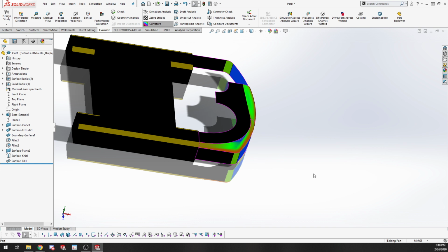Even though this is flat and this is curved, there's a nice smooth transition all the way across. There's curvature along the entire part, and the curvature gradient isn't choppy. It doesn't go from zero curvature suddenly to a radius of curvature of 160 or something like that. On some edges it does, but for the most part, when you're holding something, it's going to be curvature continuous.